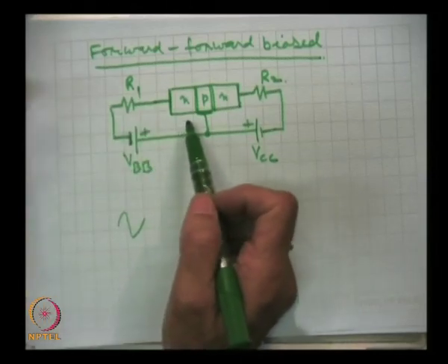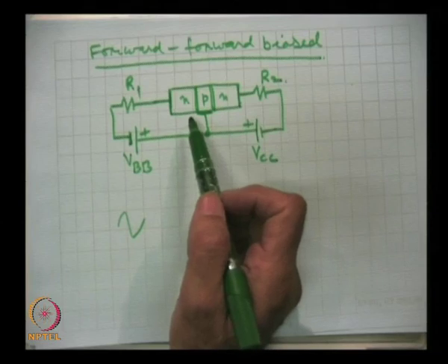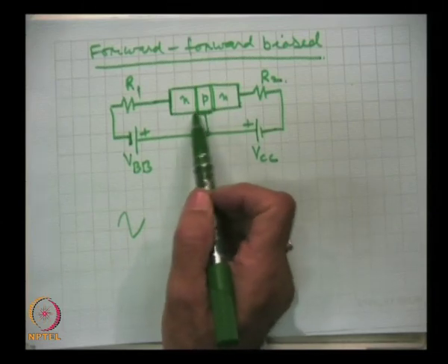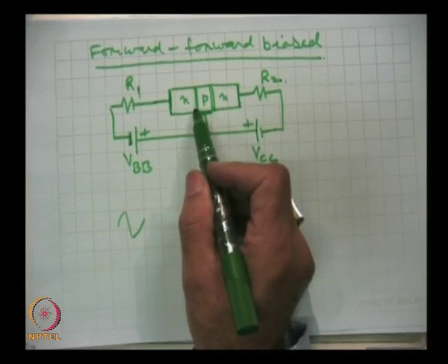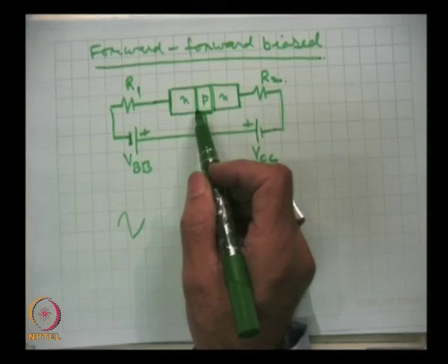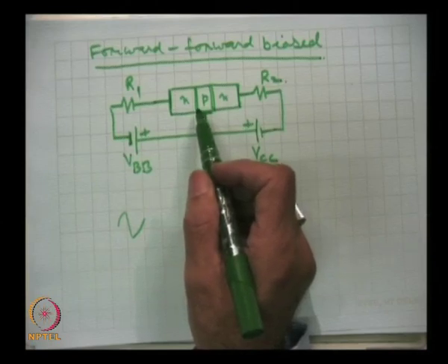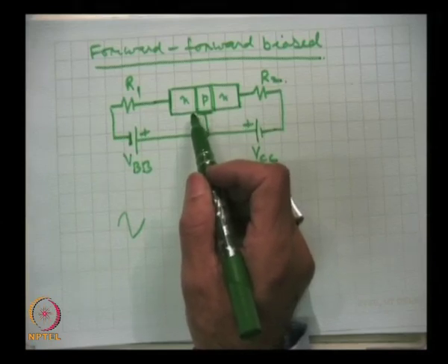What will happen? This will reduce the barrier height, as we have discussed. Now, here we can bring out our knowledge of the p-n junction, that when a p-n junction is forward biased, then a heavy current flows which varies exponentially with the applied voltage.